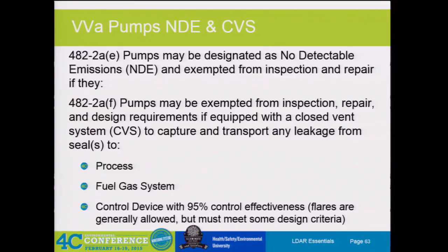Gotcha. So in Colorado, I know they've said any new device that you put in needs to be 98% control efficiency rather than 95. I don't know if any other states have come out with a new one or not. I know California is starting to write their own air rules for upstream. Ohio and Pennsylvania have new recent rules that require the LDAR stuff on those, and I think they may have included some flare stuff in there.